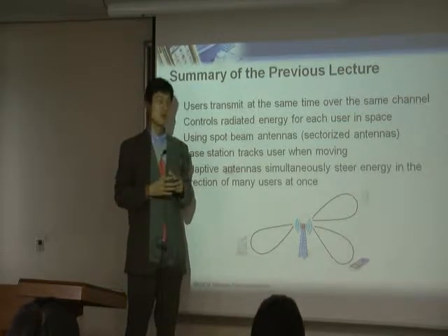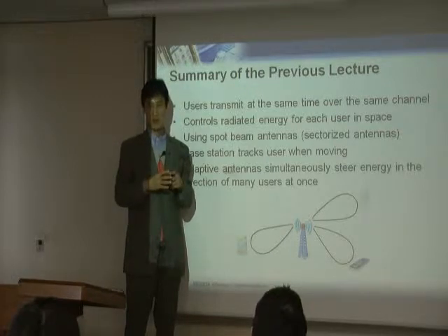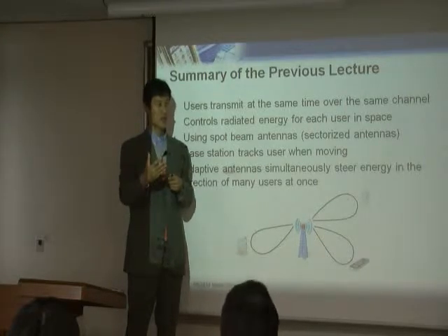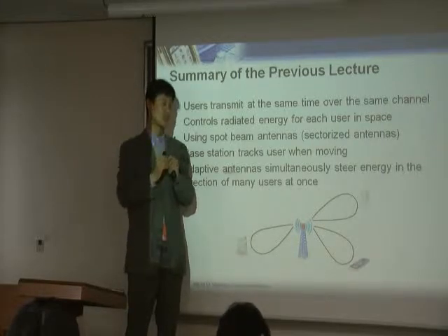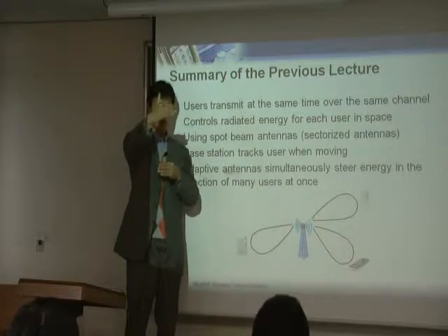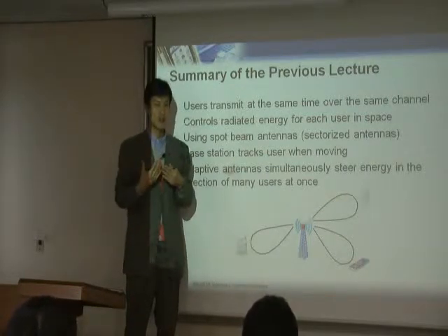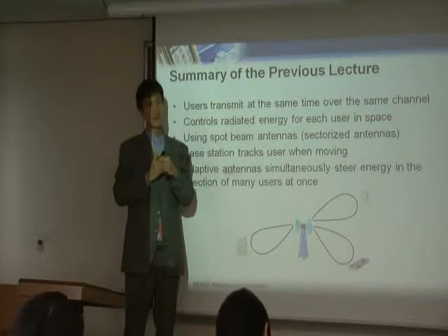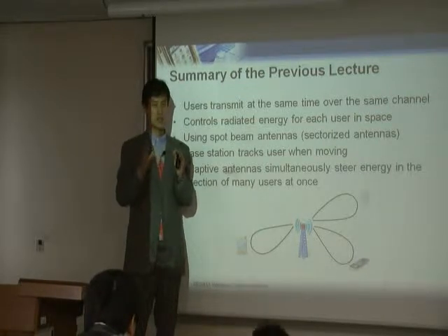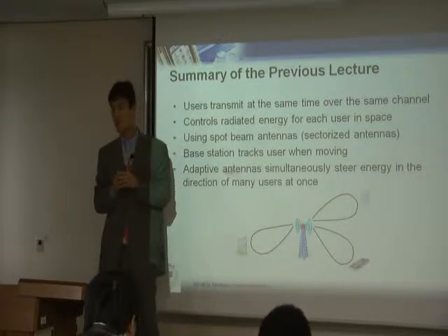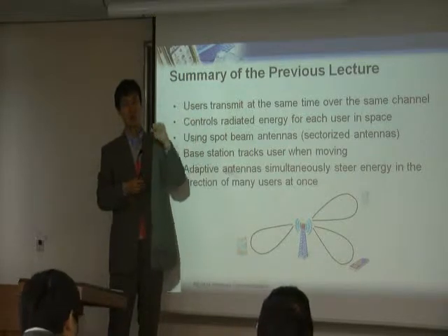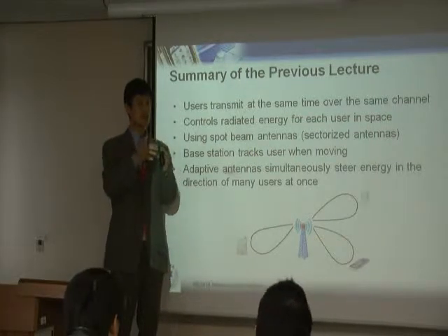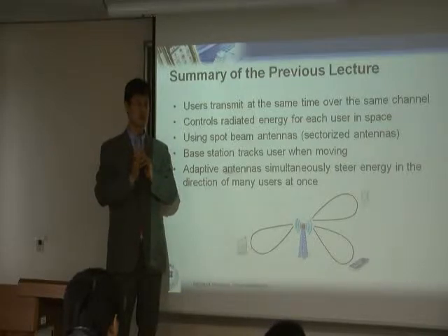So now let's say you did the time synchronization of downlink. Now your downlink time is synchronized with the base station. Then what you can do is receive the base station's messages, because your downlink time and base station time are now synchronized. Whatever the base station transmits, you can understand. So now you can receive broadcast or system messages. The system message has very important information, like what is my base station number, and the system parameters, whether I'm in SK Telecom or KT. All this information is inside the system message.